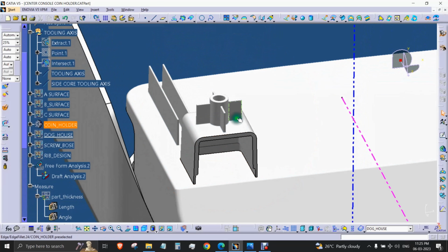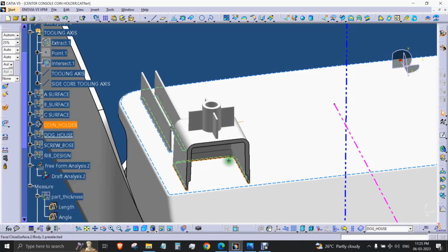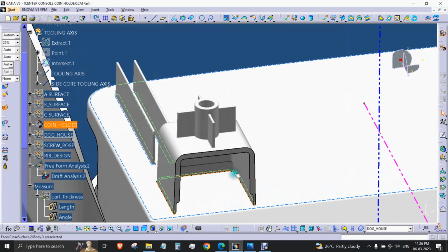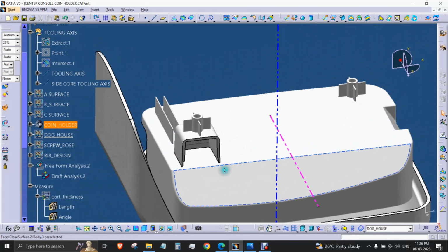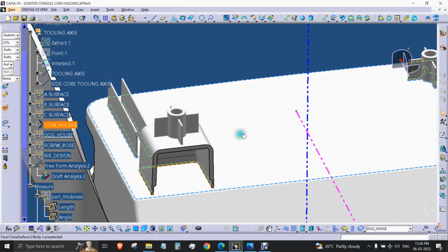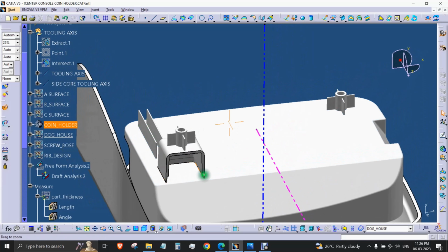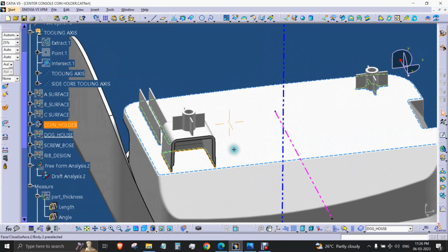And you can see a screw boss mounted over this doghouse, and there is also a reason for mounting the screw boss over this doghouse. It is also designed in such a way to avoid the seam marks on the class A surface, because if we need to create a screw boss at this height, it will certainly create several problems such as buckling of the ribs or irregularities on the class A surface.